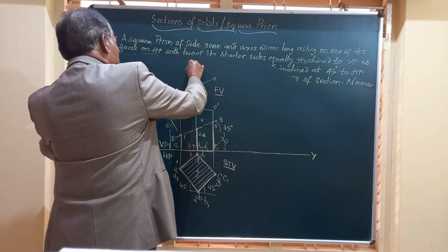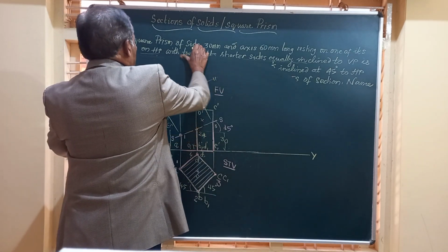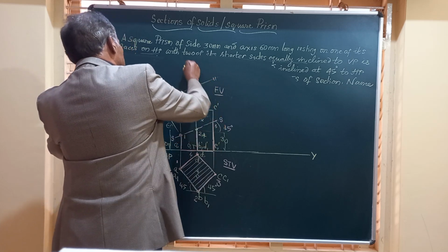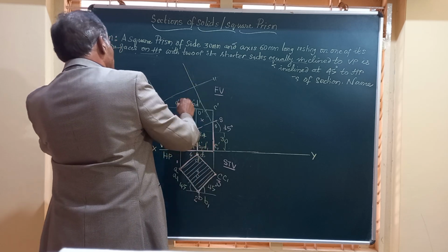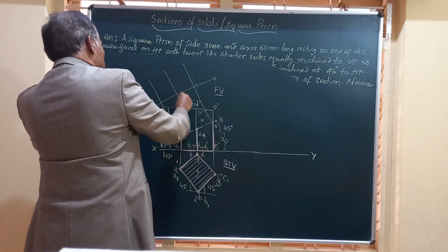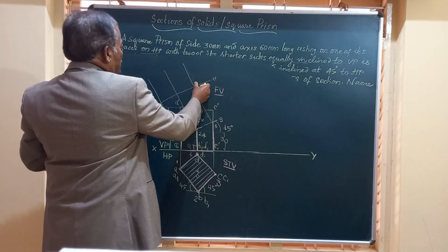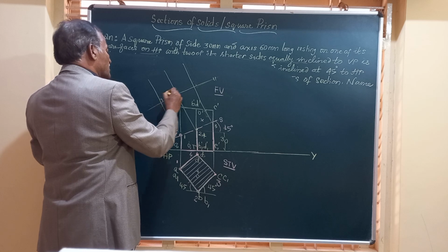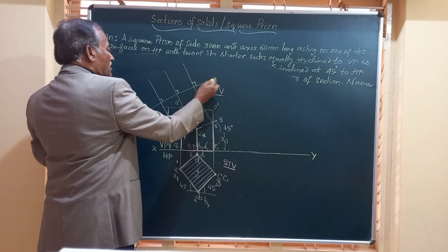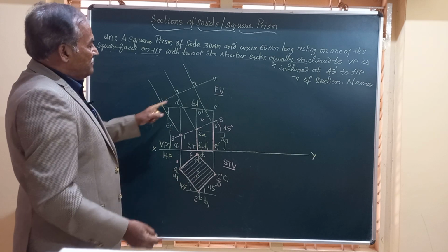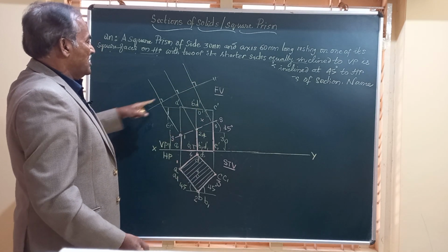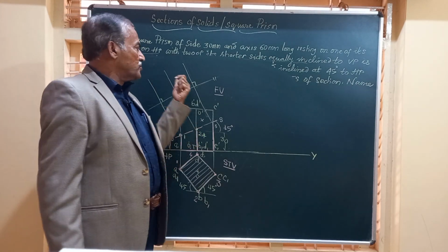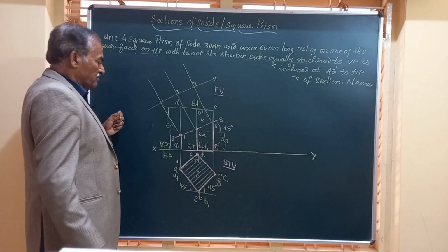So this is one line, this is a second line. From all these points we will draw these lines. Second line, from here you get 2 more. So friends, now we have to get all these 4 points on this. You should remember, these are all perpendiculars drawn to this line. SS is parallel to this; this line drawn is parallel to it. Friends, we will obtain the true shape here by taking the points one by one.